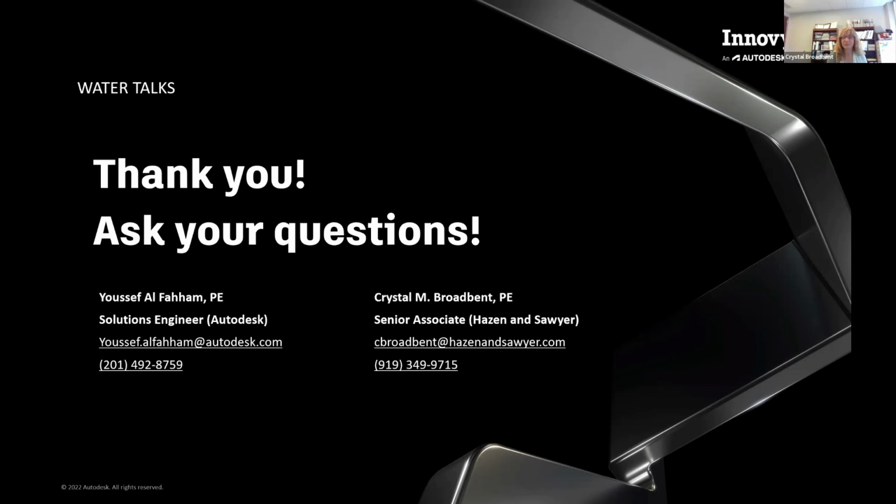We do have clients that do rely on air valves as part of their mitigation under a power loss situation. In those situations, you do need to go and actually visit the manholes or get their drawings and add that information to the model. Because they do help, they will open, they will hold the pressure nearby at least to 0. They're very localized, but I don't get a lot of good information on air valves. The other thing about air valves, I'm not against them. They come into play, they work, whether they're maintained properly all the time. So again, assuming they're not there, you provide yourself a more robust mitigation system than assuming that they're there.